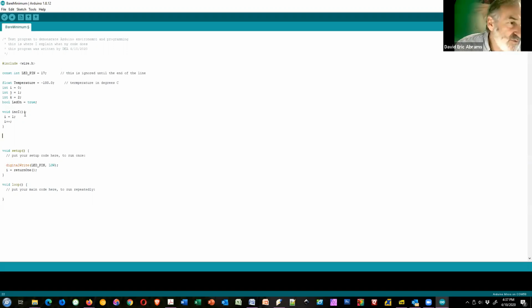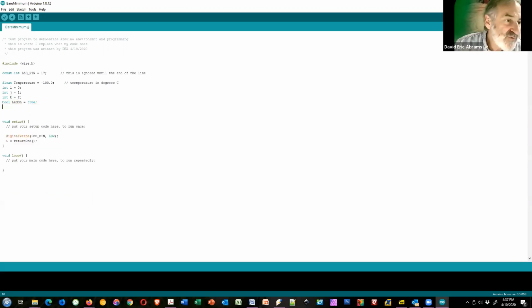One of the functions that we need to use, and we have not, so this code would not have worked, is that we have to say whether a pin on the Arduino is being used for input or output. So we need to set pin mode. This is a built-in function. Because when you start up, pins are, I think, set to input, but I wouldn't count on it.